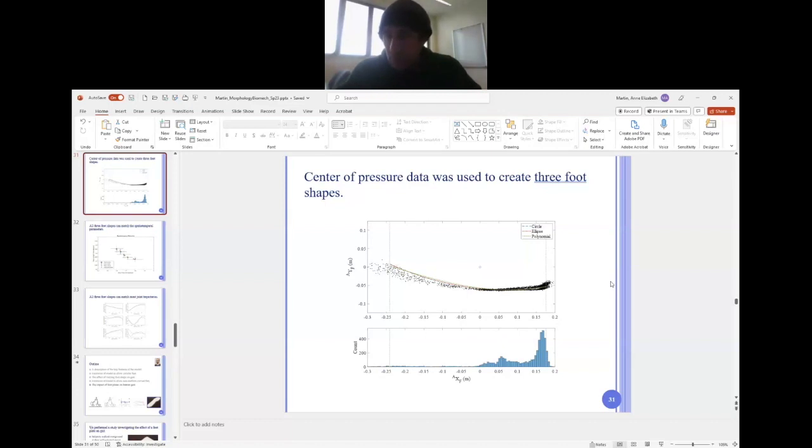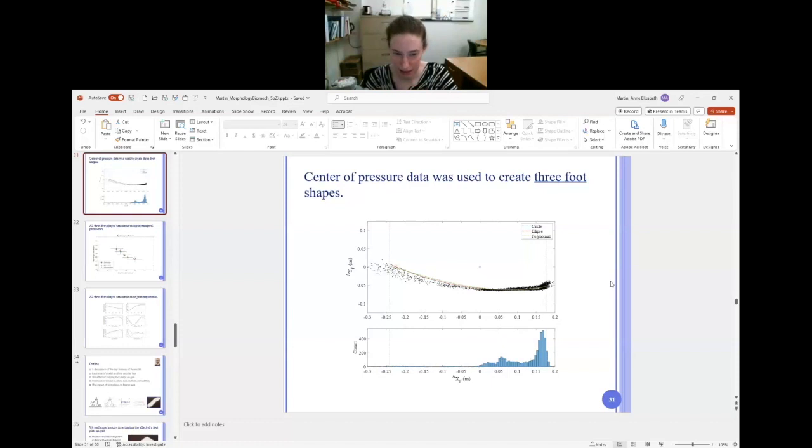Yeah, that could be a possibility. My guess is that if we really wanted to get the beginnings and ends of the steps a lot more accurate, we'd need to add in a finite time double support period, which is possible. It makes doing the simulations a whole lot harder. I didn't talk about it in this talk, but one of my previous grad students looked at including a finite time double support period, and it makes all the simulation and finding the gaits enormously harder.